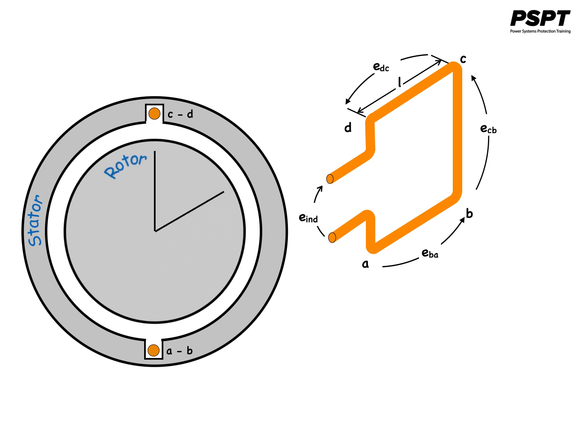This slide shows a rotating rotor with an angular velocity of omega having a sinusoidal distributed magnetic field in the center of the stationary coil. Notice that this is the reverse of the situation previously studied, which involved a stationary magnetic field and a rotating loop.